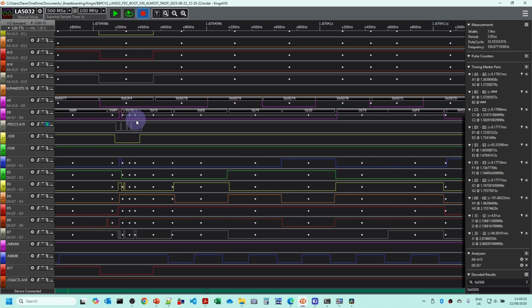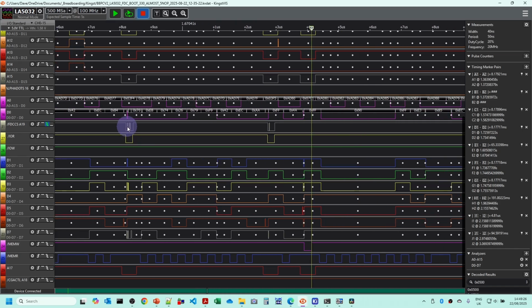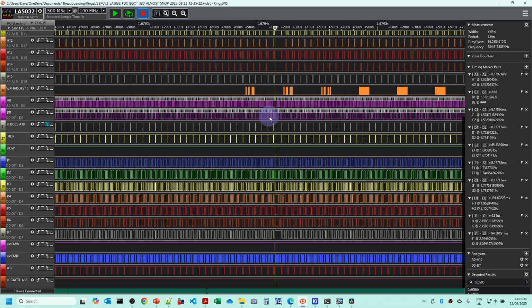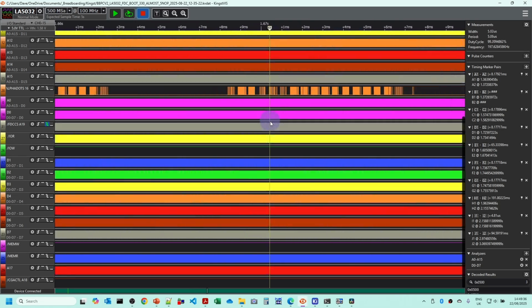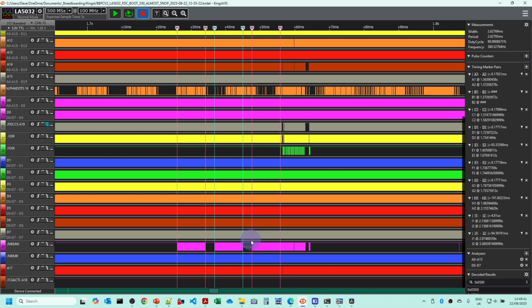It's causing the code to think that there is a value here to read. So there's something strange going on to do with the status polling here, either interference or some other reason, which is causing the code to read the data from the floppy disk controller when it obviously doesn't have any ready. And then it means that all of the subsequent writes to the disk further on down here are occurring at the wrong point.